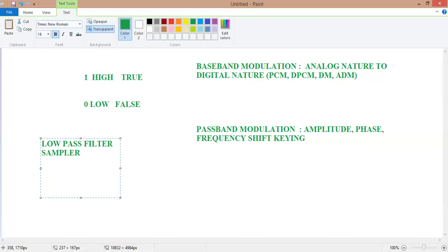What is aliasing error? I will tell you later in our discussion related to baseband modulation. But that aliasing error may be found in terms of some overlapping, which is completely undesired, and you will get the wrong information from the correct input. The elimination of that error by using a certain filter is called the anti-aliasing filter, because aliasing error may be eliminated by this filter.